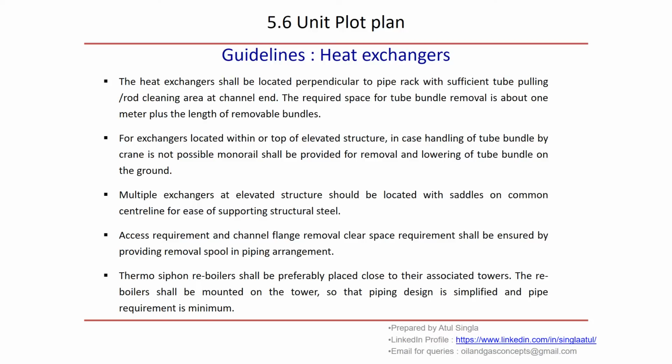The guidelines are captured here. If you see, the heat exchanger shall be located perpendicular to the pipe rack. This is the first requirement. Whenever we are locating the heat exchanger, it should be perpendicular to the pipe rack with sufficient tube bundle and rod cleaning area at the channel end.